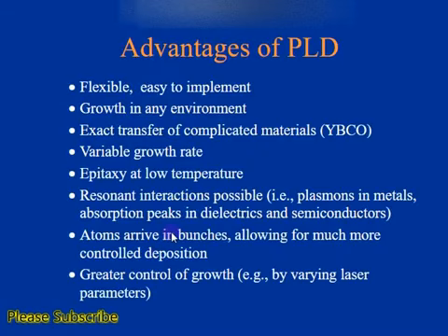PLD is a very flexible technique, easy to implement, and one important feature of this is the growth can be carried out in any kind of environment, and you can have a variable growth rate, because it has multiple parameters through which you can control the growth rate. Similarly, exact transfer of complicated material can also be deposited through the PLD technique. Epitaxial growth can also be accomplished at low temperature, and resonant interaction is possible because atoms arrive in bunches, allowing for much more controlled deposition.